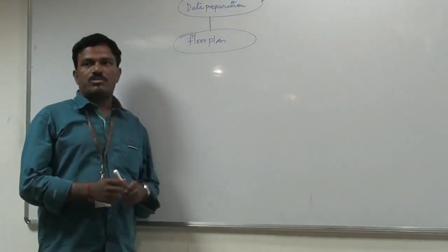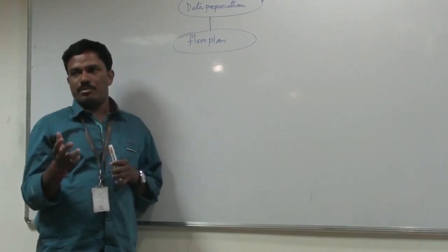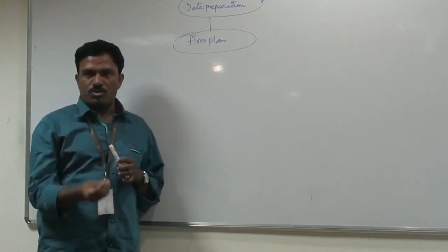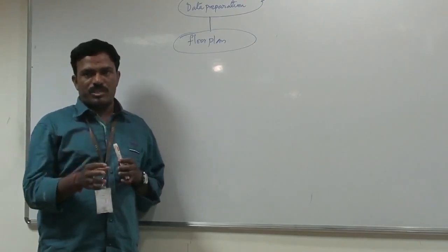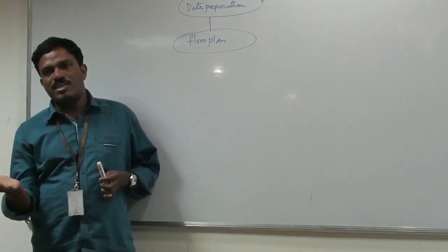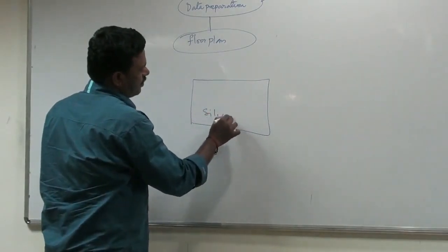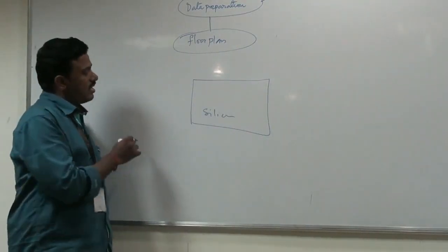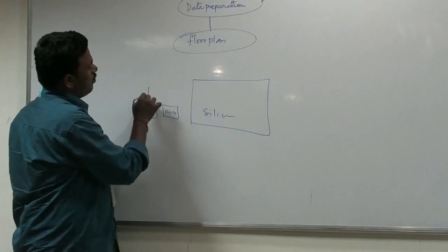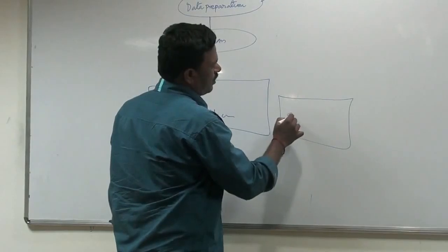So assume you are just going for the new house. You have some additional stationaries like cart, right, bureau. So before placing all those items into your house, we need to visit the hall size, bedroom size, right? And we have to see where actually I can place my bureau, where actually I can place my cart, right? In the same way, we have some specified silicon. And also we have some hard macros like RAM, ROM, PLL, right? Hard macros, and also soft macros of your block.